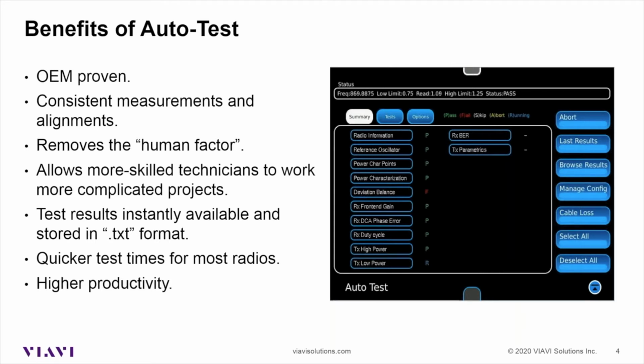And here's the thing, if you're testing that radio at 1 or 2 frequencies, that's fine for those 1 or 2 frequencies. But when you issue that radio, the end user may not be using those frequencies. So let's say you test the radio in the middle of the band, and they're actually using it at the fringes. Well, one of the things we've seen historically is that radios tend to perform great in the middle of their frequency range. You get them out into the edges of that frequency range, and all of a sudden you start seeing a roll off in sensitivity, or you see their transmit power kind of starts to drop off a little bit.